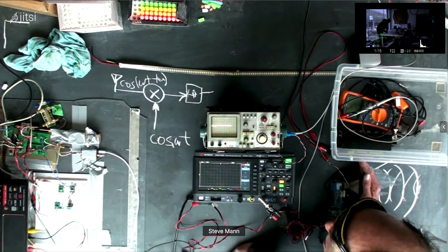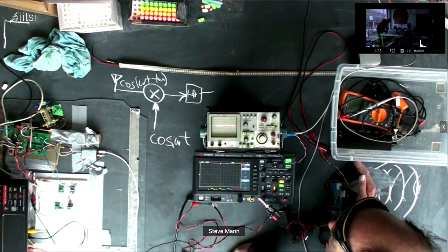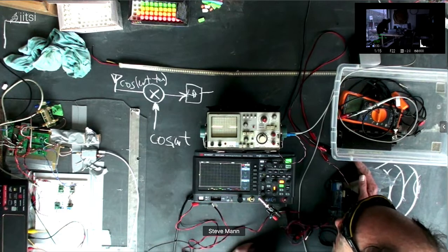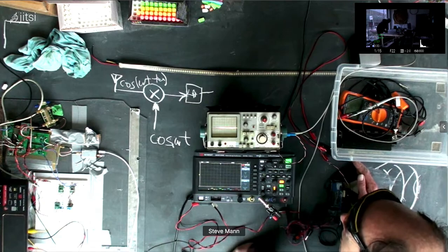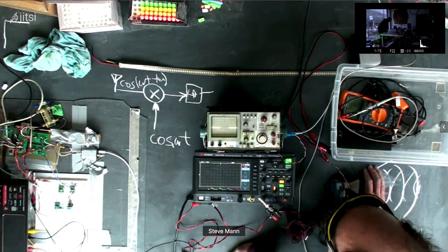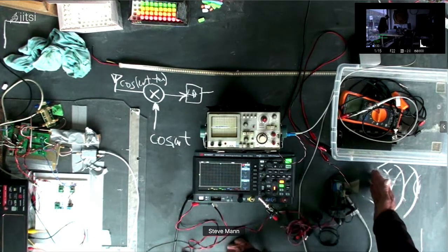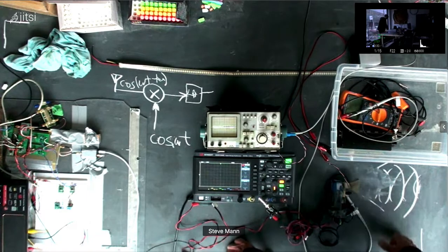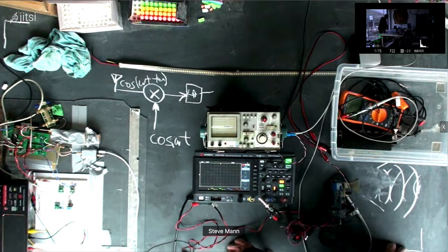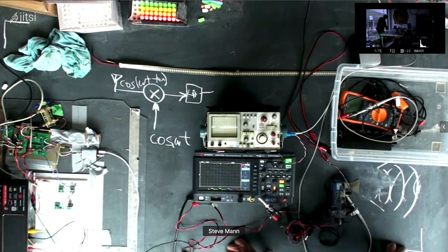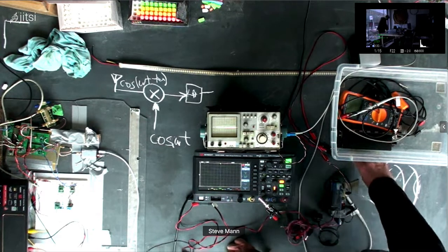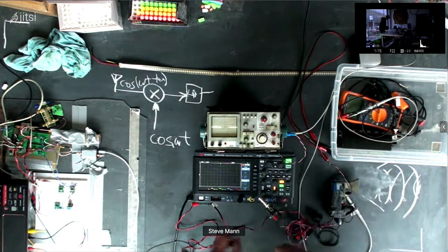The movement is in proportion to the speed of light, so the ratio between the speed of my hand and the speed of light is the same as the ratio between the received signal frequency and the 24.36 gigahertz that's coming out. So the fraction of my speed with respect to the speed of light is the fraction of the frequency with respect to the frequency of the radar, which is transmitting at 24.36 gigahertz.